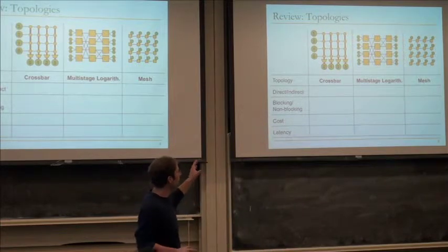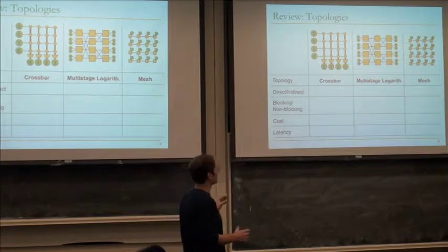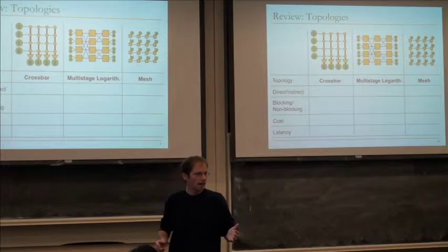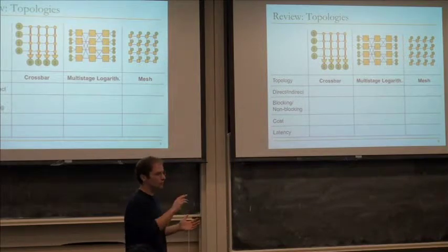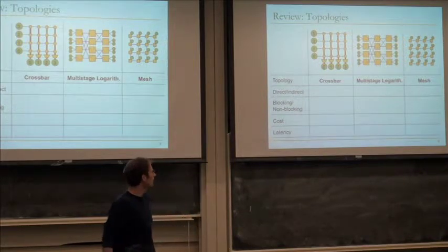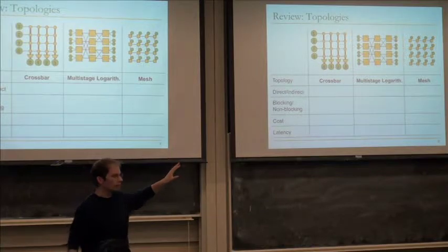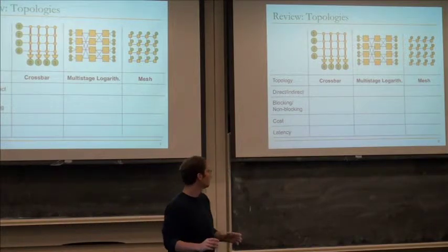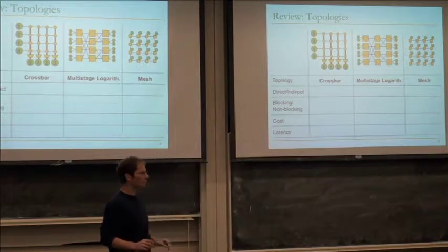And that connects to a router. And all of these routers connect together just to their neighbors, so north, east, south, west, for example. And when a packet moves, it just moves through the mesh along these links. And so the advantage of a mesh is that we get really good scalability because you only connect to your direct neighbors. You don't have global wires, for example, like you do in a crossbar.